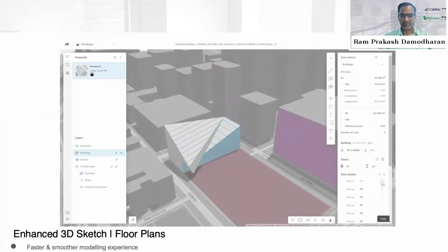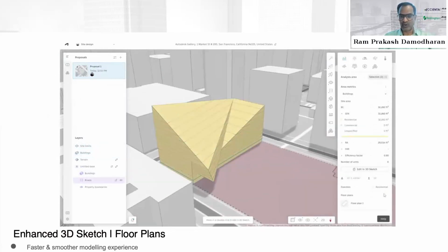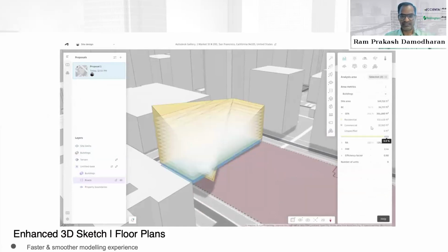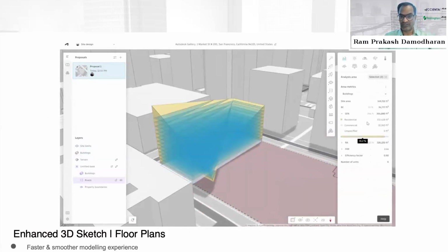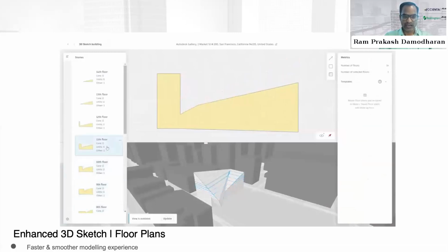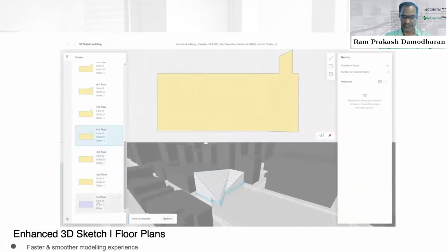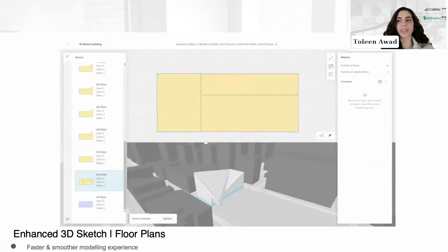So when you're doing this kind of massing studies in a normal Revit on a normal single desktop, you face a lot of hurdles when it comes to high-rise towers. And as you mentioned, Revit, we can use it for a lot of detailed structures. Since Autodesk Forma is a cloud platform, you have no hurdles using the model at any level or any design options, and you can also seamlessly take this Forma model into Revit and back and forth as well. Indeed.